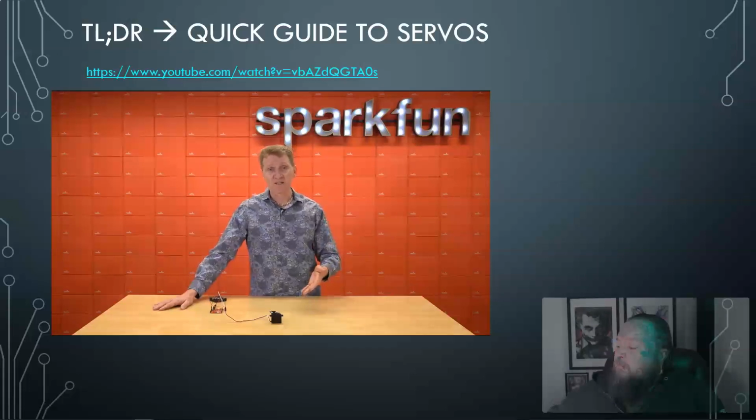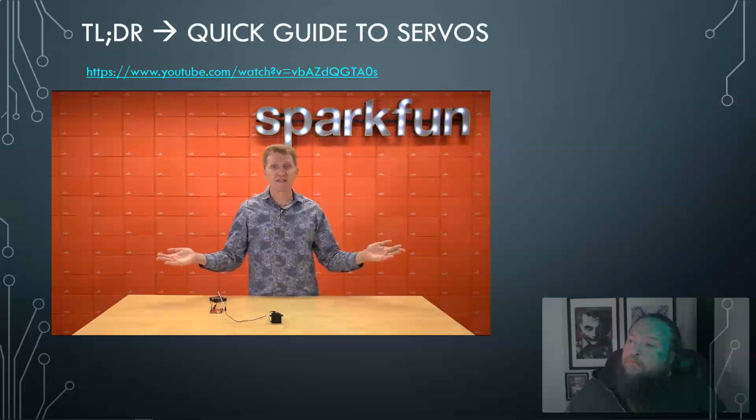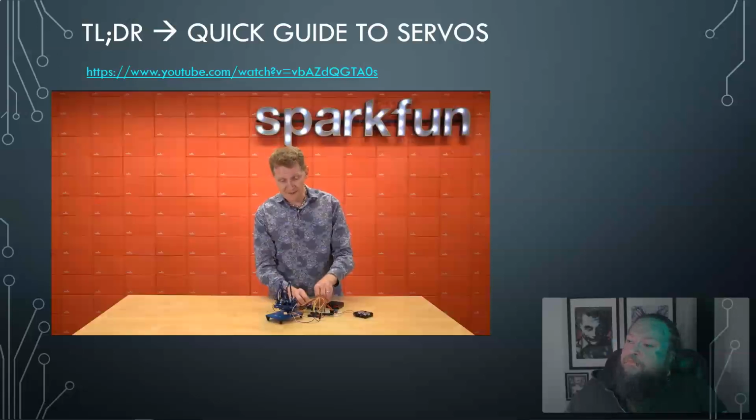Whereas with the continuous rotation, the number sent is its speed, 90 being no speed at all, and then the further you get, either down or up from 90, determines how fast you go. Further away, faster speed. Servos, like I said, can also be controlled manually. And they're great for robotic arms like this one.